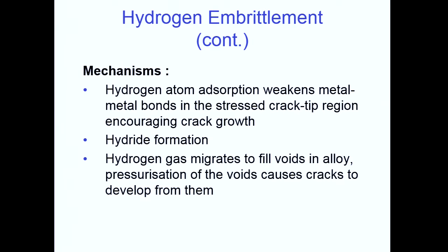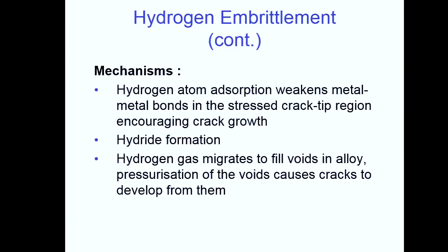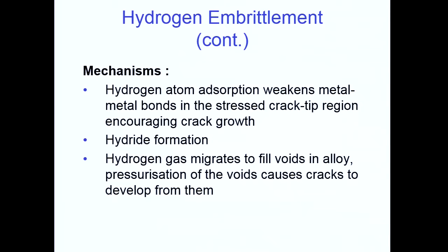And so you can think of this just like the formation of an oxide. Okay, in this case it's just produced a hydride, and it does the same things that an oxide does. Do you remember the volume of the corrosion product is greater than the volume of the parent metal? The volume of the hydride is greater than the volume of the parent metal, so the whole thing expands. And we did some experiments some time ago, and we were using palladium cubes.